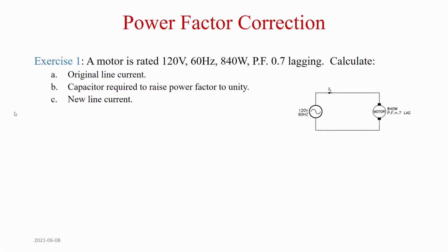Here's now this question. Now what I'm gonna do is part B first, just to show you the procedure of increasing the power factor, improving the power factor. So what do we have? We have old, which is the load only, the motor only. New is the motor with the capacitor.